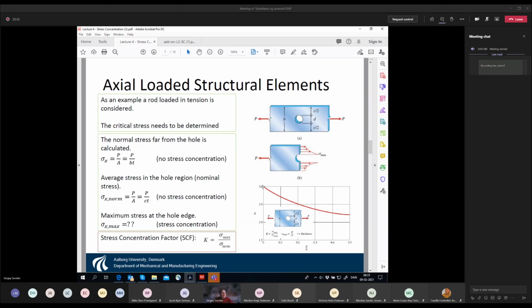So it's a very complicated thing, but then what you get, for example, for this simple case, you are able to have the exact analytical solution of the problem of stress distribution. And in this exact analytical solution, this ratio D divided by B stands as a parameter. And then you may just take this parameter to the limit that it equals 0. And then you have this magic number 3.